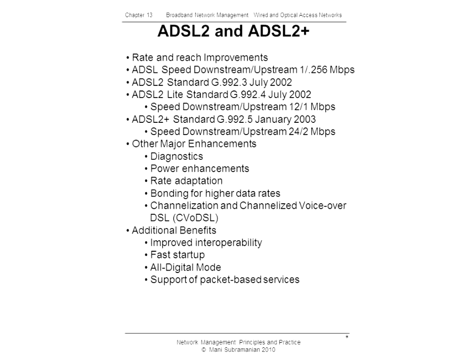Now in case of ADSL2, modulation and framing layers are decoupled, which enables the transmission data rate to be changed without affecting the framing layers, and therefore the data rate is changed based on the extent of external disturbing effects of crosstalk and other parameters such as radio, temperature, and water, etc.